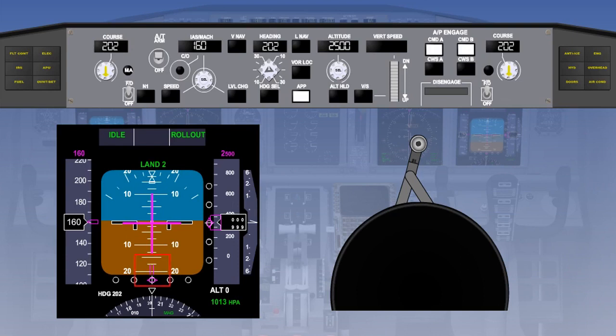Some aircraft may use a runway guidance system, giving the pilot commands to move the rudder left or right to maintain the centerline. With rollout control, the autopilot will remain engaged until the pilot disengages it at some point during the rollout.